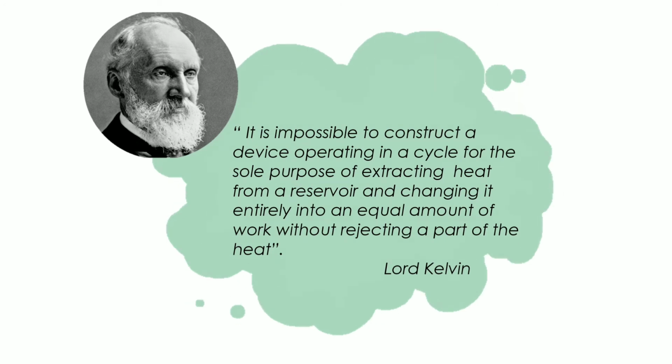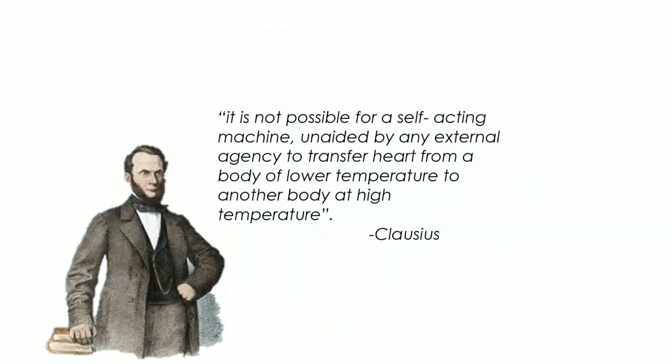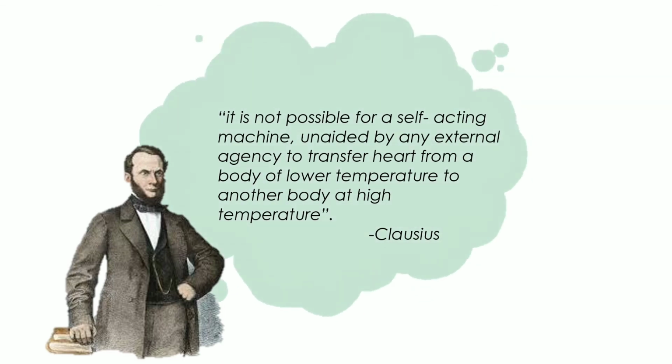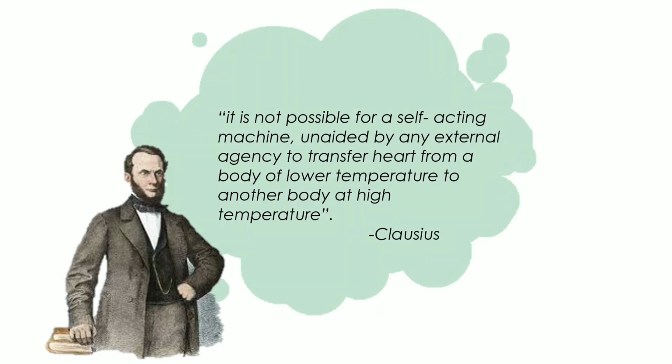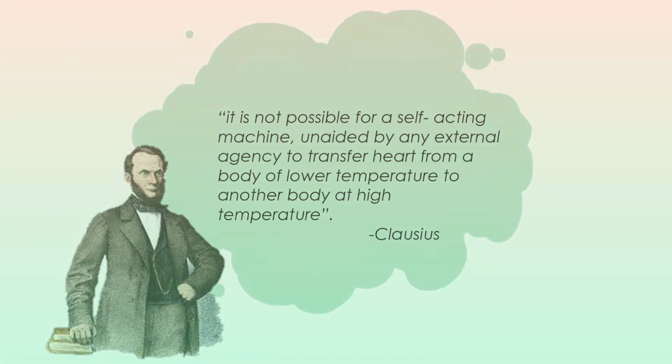This statement simply means an engine can convert only a part of the heat energy into mechanical work. Clausius stated that it is not possible for a self-acting machine, unaided by any external agency, to transfer heat from a body of lower temperature to another body at higher temperature. This statement also means no heat engine is 100% efficient.